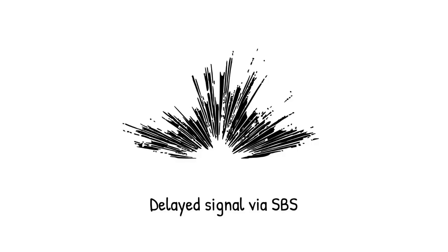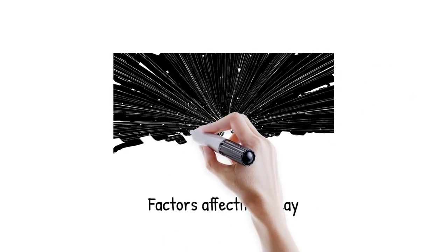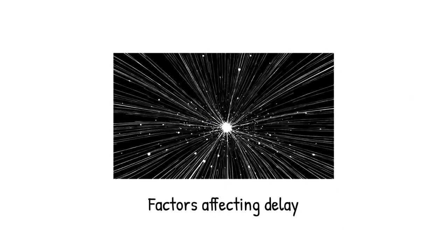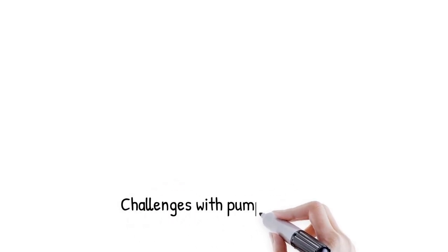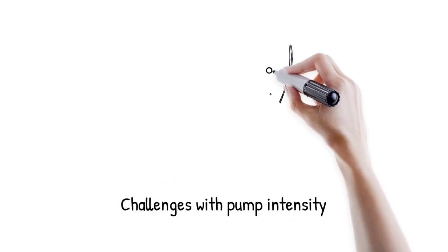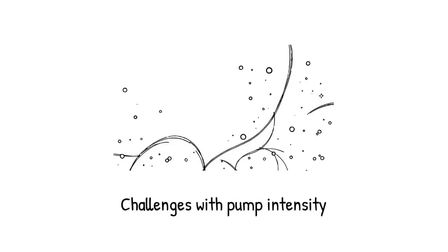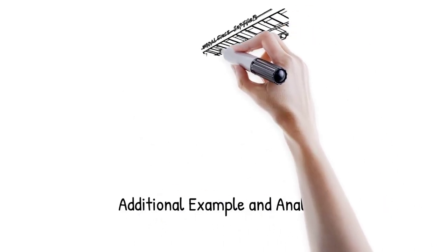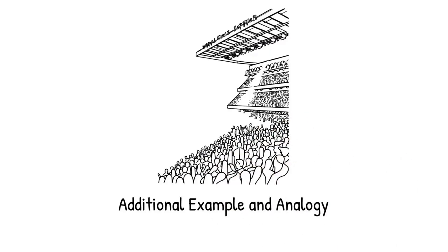The delay is proportional to pump power and interaction length, but limited by phonon lifetime, about 10 ns in silica. Achievable delays of tens of nanoseconds are practical in telecommunications fibers with modest pump powers, about 100 mW. However, increased pump intensities raise noise and can induce nonlinear distortions. Engineering specialty fibers with higher Brillouin gain can enhance delay without excessive pump requirements. A 1 km highly nonlinear fiber produced a 200 ns delay at 1550 nm using a 200 mW pump.